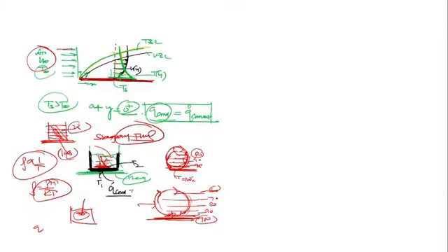So here in this case Q conduction should be equal to Q convection, again the same phenomena as I told you here. Now I think one question would arise in your mind: sir, if this is the case, then in the fluid there will never be conduction. Whenever I'm talking about the fluid, either stationary or in motion, there is always convection, because even if the fluid is stagnant, due to the difference in temperature there is a difference in density, and that causes induced motion, and that causes the convection heat transfer.